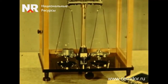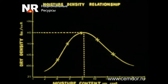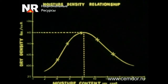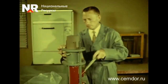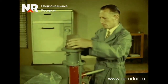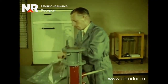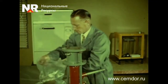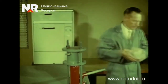A graph is plotted showing the relationship between the dry soil density and moisture content. For cohesive soils, the maximum density value and the corresponding optimal moisture content are determined at the highest point of the graph. To determine the optimal dosages of stabilizer and cement, several mixtures of different compositions are prepared, varying the content of the added components. This is done with a specific increment. Samples in the form of cylinders are prepared from these mixtures by compaction. The compaction is carried out to achieve maximum density at the previously established optimal moisture content.